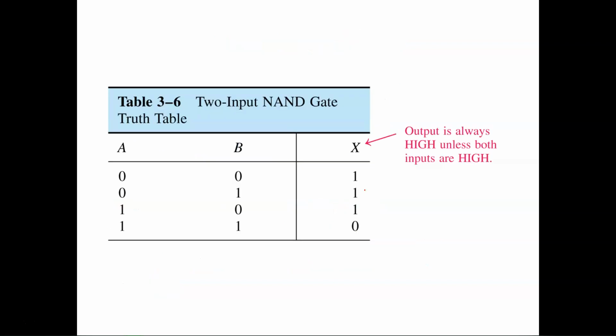Okay, so going back to this real quick, the AND gate. If I was to show you the truth table for the AND gate, A is 0, 0, 1, 1 and B is 0, 1, 0, 1. The AND gate's logic is always off until both signals become high. So the best way you can memorize how the NAND gate works is that his signal is the opposite of the AND gate.